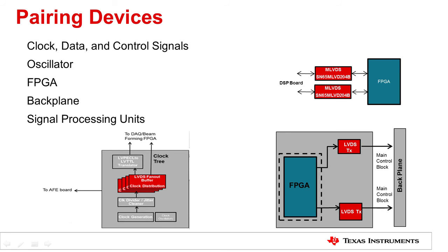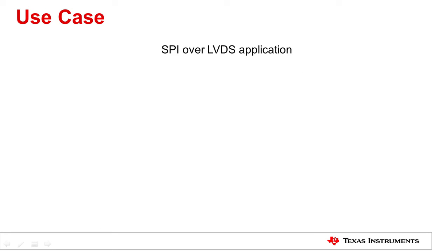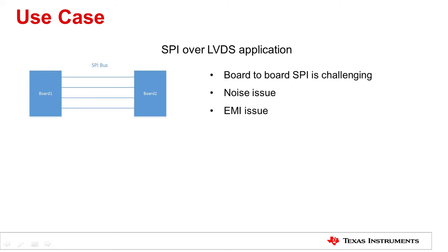One specific use case demonstrating LVDS devices' capability is the support for the SPI bus, which consists of both clock and data signals. It can be challenging to send SPI signals off-board from your microcontroller to a remote board for several reasons. Signal integrity becomes a big concern due to reflections caused by unterminated signal lines. It is also less immune to external noise, which may cause communication errors.